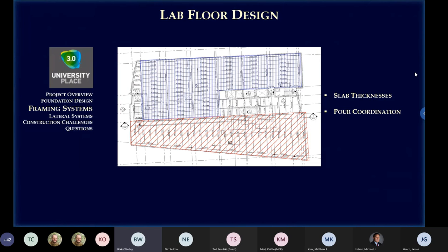The lab spaces were designed for a slightly higher live load than the office spaces, and the owner's team was also aware that some of their prospective tenants could have sensitive equipment and higher expectations of floor sensitivity in the lab area. And so in this area, we were looking at increasing the floor stiffness and also increasing the floor dampening.